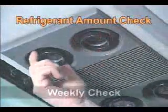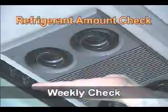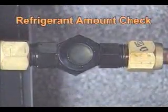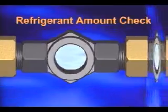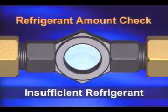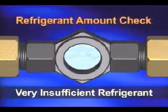Low refrigerant causes poor cooling performance. Check the refrigerant every week. The refrigerant amount can be checked through the sight glass after turning on the air conditioner. When there is enough refrigerant, you'll see no bubbles in the sight glass. A few bubbles means that there is insufficient refrigerant. Many bubbles means that there is very insufficient refrigerant.